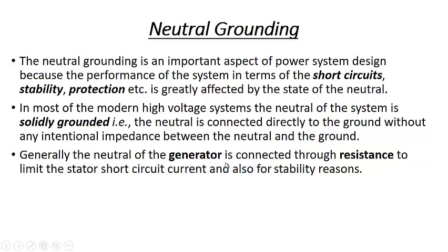Generally, the neutral of the generator is connected through a resistance to limit the stator short circuit current, and also for stability reasons. You'll always see that a generator, a synchronous generator particularly, will be connected to the ground through a resistance. It is for the purpose of reducing the short circuit current and improving stability. So this is not a solidly grounded system, this is a resistance grounded system.